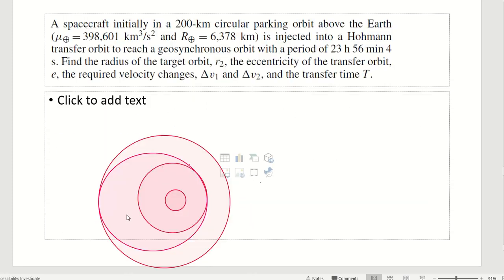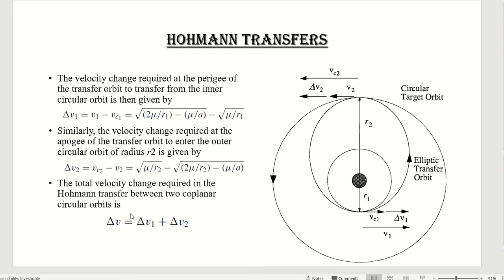I will just move backward. Just look at this. This was the formula. This is the transfer orbit velocity for the elliptical orbit, and this is the circular orbit velocity. Then the final circular velocity for the second transfer, at this point, minus the transfer orbit elliptical velocity, this one. So where it is circular there, here it is an elliptical orbit instead. That's the difference.